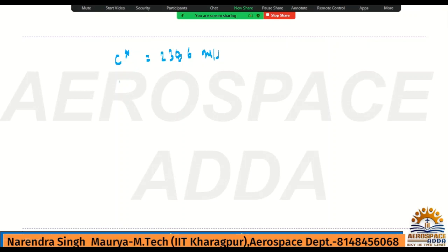ISP they have given to us, 455 seconds. Based on this we need to find that value. C star we have in terms of combustion pressure P0C and A_t, throat area, divided by mass flow rate of the propellant. This is formula 1 for C star.